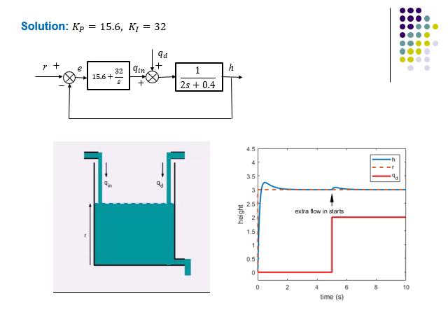Initially the height of fluid increases quickly, we get a small amount of overshoot, but there's no oscillation in the level of the tank, and the settling time is quite short. Also, although we have this extra flow coming into the tank, you can see that this causes a small error, but then the error reduces back to 0. So we've got a good solution here for the PI controller.